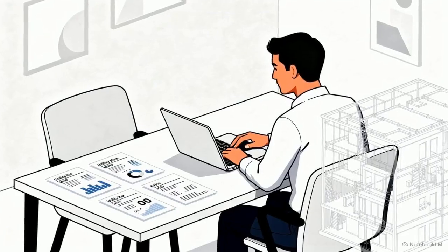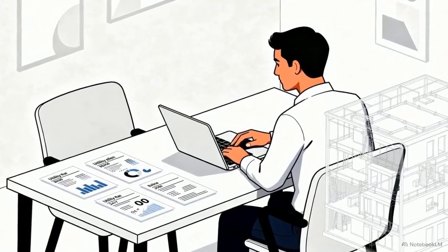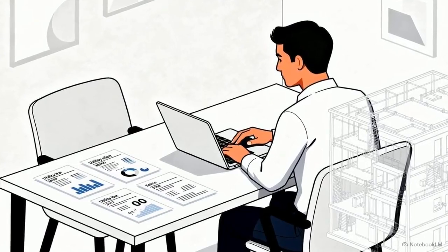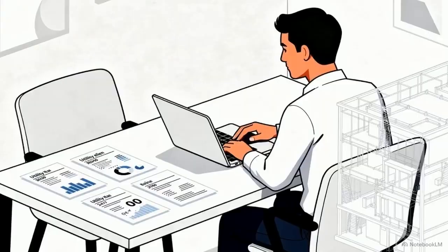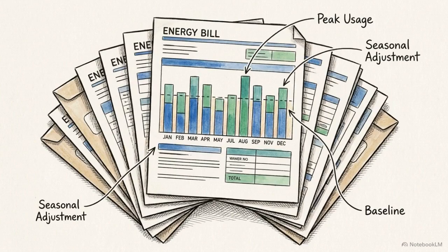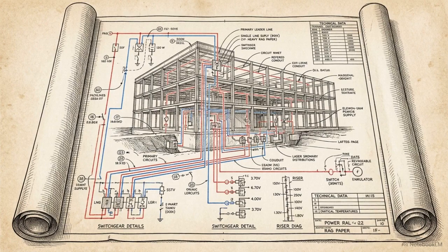Step 1 is desktop data collection. Gathering structural and historical data remotely minimizes the time and manpower required during physical site visits. Secure the essential documents upfront. You need a full year of electrical energy bills to establish a consumption baseline and the single-line power supply schematics to map the distribution. Standardized data collection forms organize this raw documentation and ensure no critical variables are missed before